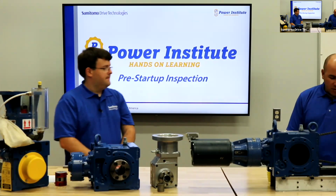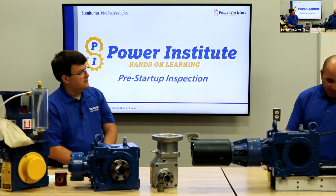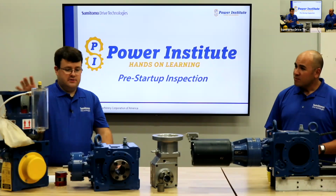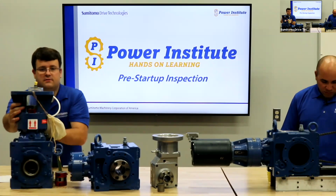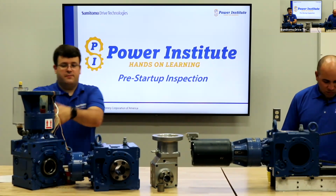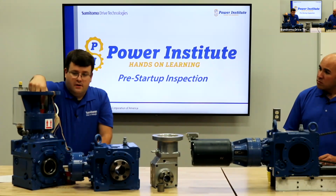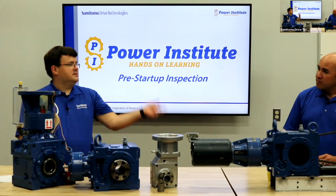Okay. And then a couple more questions. What would be the best way to check rotation if there's a backstop? Check it without the motor being powered. What if the motor's already connected? If it's already connected, make sure there's no power going to it. I'll use this reducer as an example. With our safety guard removed, you can go in here and turn the shaft. If there was a backstop on this unit, it would only go in one direction. This one goes both directions. If I go to turn it, it would hit that and stop, so you would know which direction you're going. You mark it counterclockwise or clockwise, and then run your motor separately and see which way you're wired for.